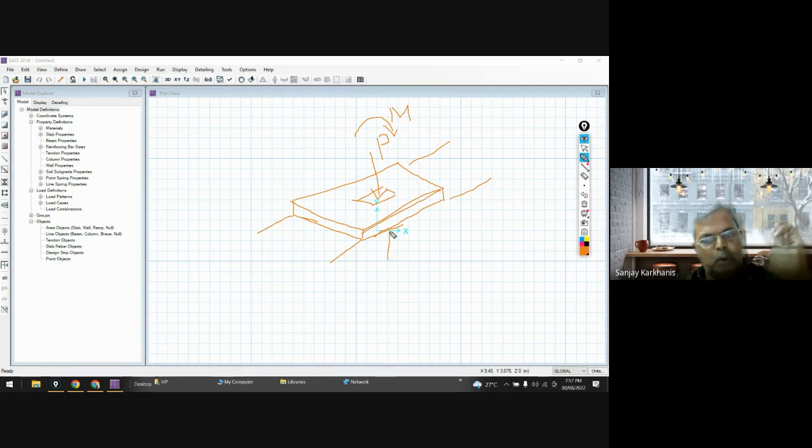Now soil is providing upward pressure based on its bearing capacity. It will be exhibited something like this. But soil is not a homogeneous material, right? So because of that, some settlement is allowed, and there is a settlement. That's why we considered all these as a spring.